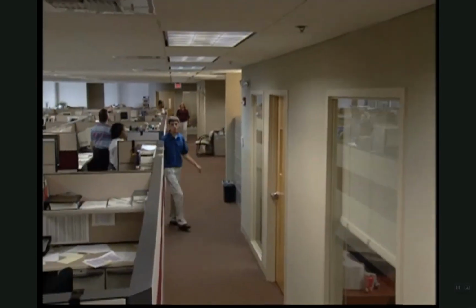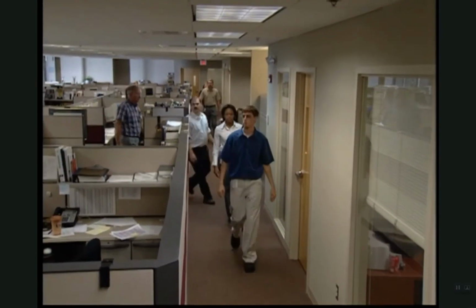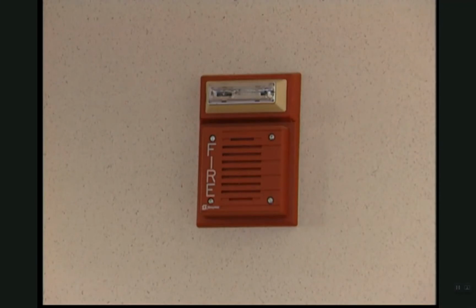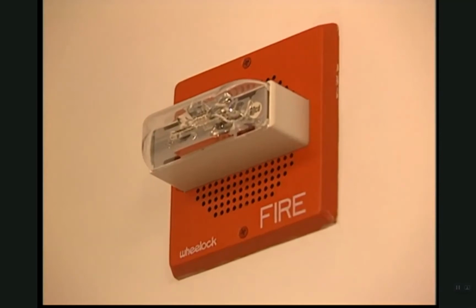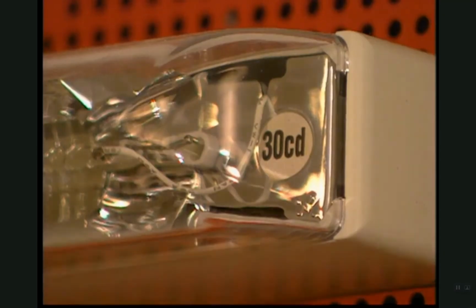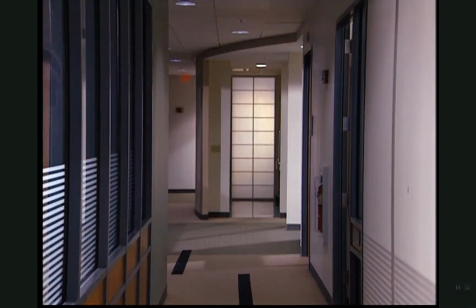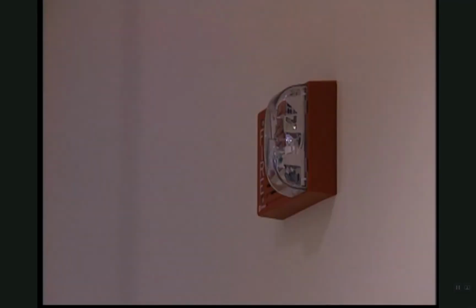Notification appliances are designed to alert building occupants and others of a fire alarm condition. The alarm is usually a combination of a flashing strobe light and a repeating pattern of loud horn, buzzer, or bell sounds. Typically 3 blasts, followed by a pause, then repeating again. This pattern is the universal evacuation signal, known as the temporal 3 or 3-pulse pattern.